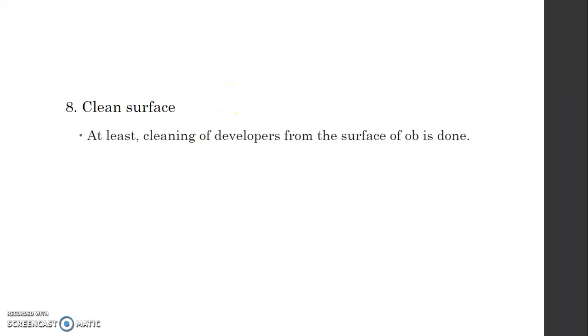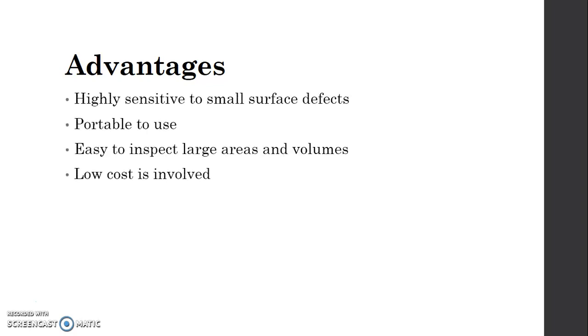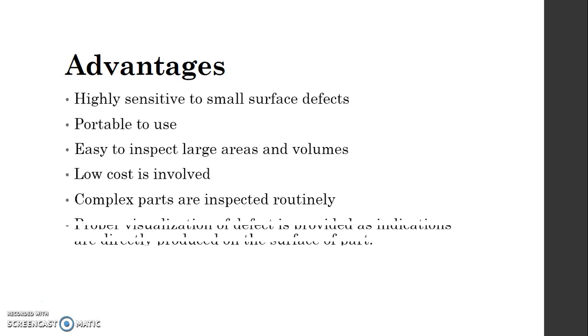Because we have applied the developer, no? So we have to clean the surface. That's very important. So these are some of the important steps. Viscosity is a characteristic of the penetrant, and the capillary action we already discussed. Okay, and the advantage of this liquid penetrant testing is that it is highly sensitive to small surface defects, and it